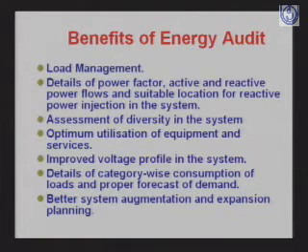Now, coming to the benefits of energy audit, it would help us in load management. It will also tell us what is the power factor of the system, what is the active and reactive power flows, and suitable location for reactive power injection in the system, and assessment of diversity in the system, optimum utilization of equipment and services, improved voltage profile, details of category-wise consumption of loads and proper forecast of demand, and better system upgradation and expansion planning.